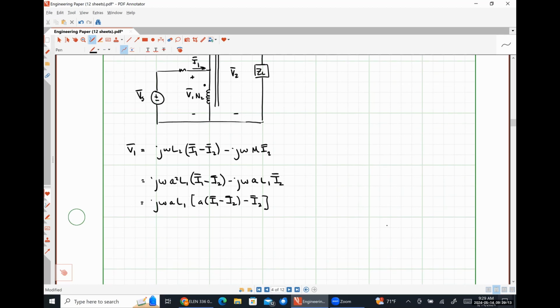So you see these in a lot of distribution substations. And again, they're used in applications where we don't need electrical isolation between the primary and the secondary because they are literally physically connected together. It's the same coil.